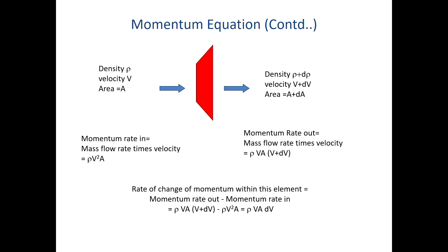So all the molecules inside have experienced some forces. These forces can be pressure forces normal to the wall, viscous forces normal and tangent to the walls. When I say wall, I'm talking about the left boundary, right boundary, but also all the lateral boundaries, the slanted surface. Then you can have body forces such as gravity, electrical forces, magnetic forces.